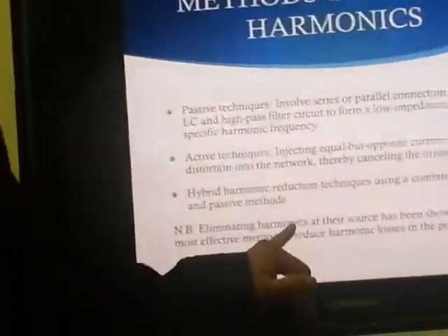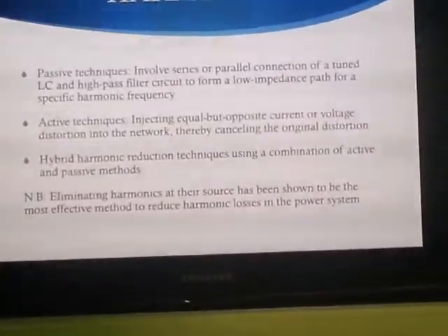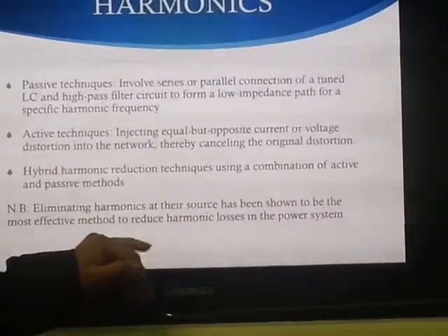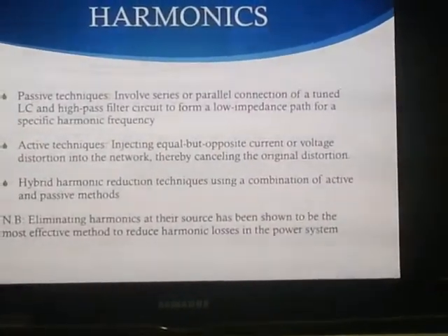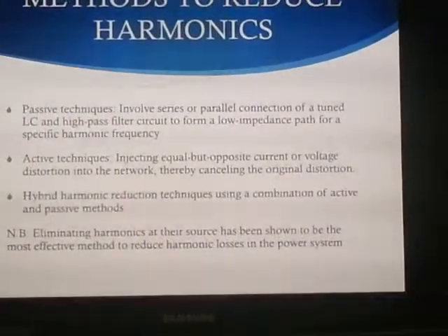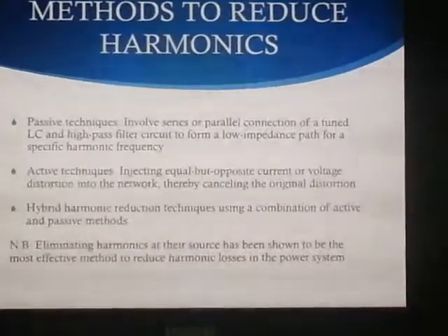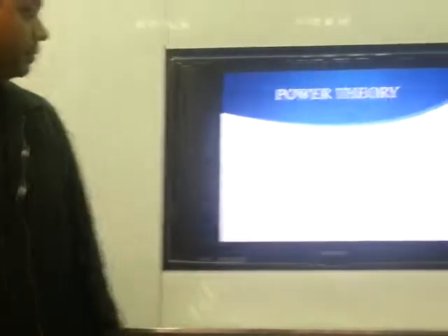There is a note here: eliminating harmonics at their source has been shown to be a more effective method to reduce harmonic losses in the power system, which means that reducing the harmonics at the supply end is beneficial compared to reducing them at the load.